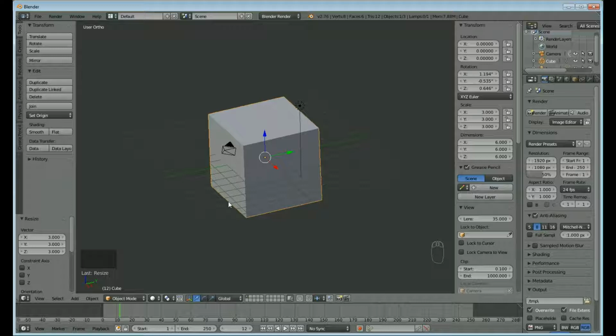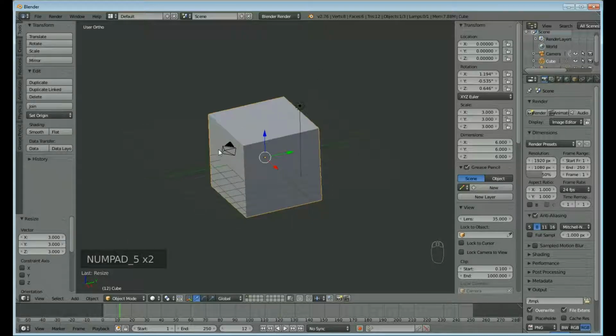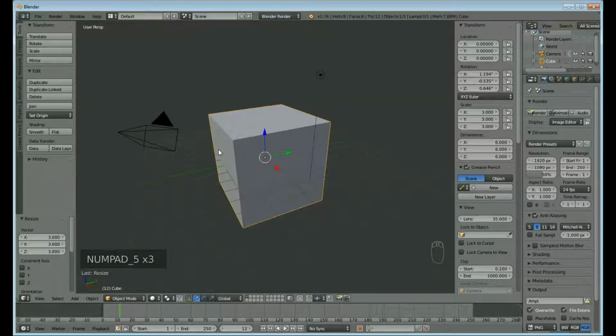So when you see a side which is 5 meters, and that's 5 meters, because of the distance you expect that to be smaller. However, when you are working with the model, sometimes you like to see the actual sizes rather than the sizes you see in real life. So that's why you can press number 5 on your num key to toggle in between. So you press 5, work on your model, press 5, and then it gives you the real rendering, the real 3D representation of the cube.